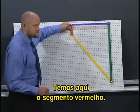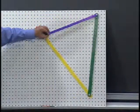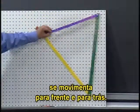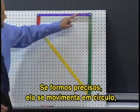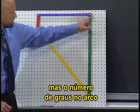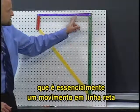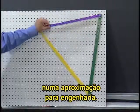What we have here is the red link. If it goes around and around, the farthest end of the green link essentially just goes back and forth. Now, if we're being precise, it's moving in a circle centered at this location, but the number of degrees in the arc are so few that it's essentially a straight line motion to engineering approximation.